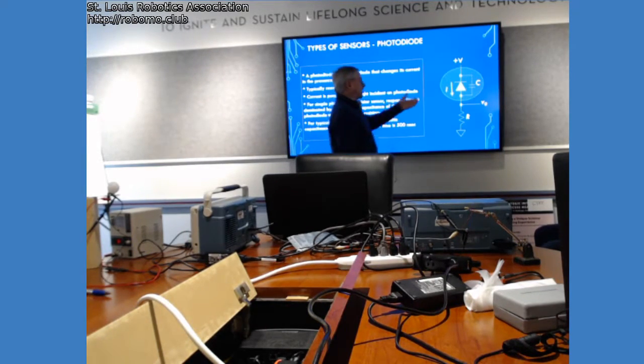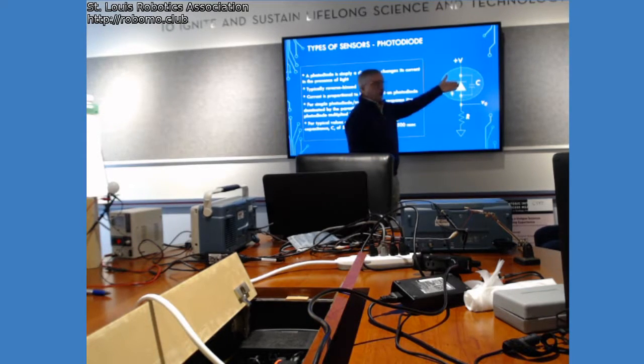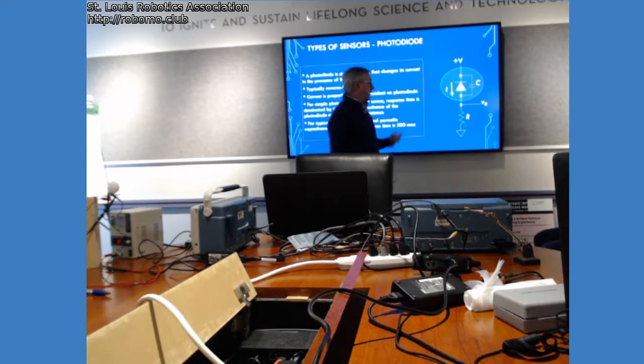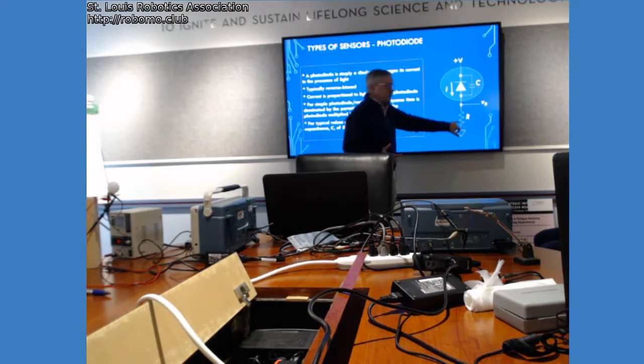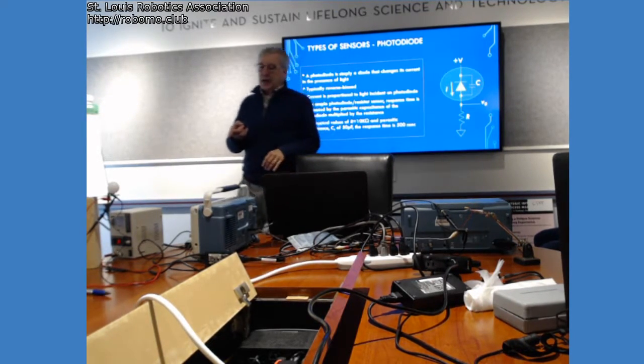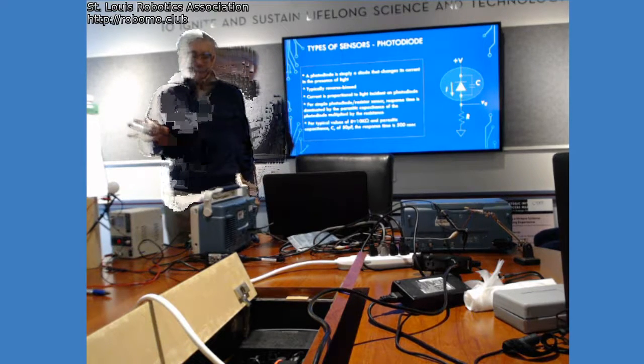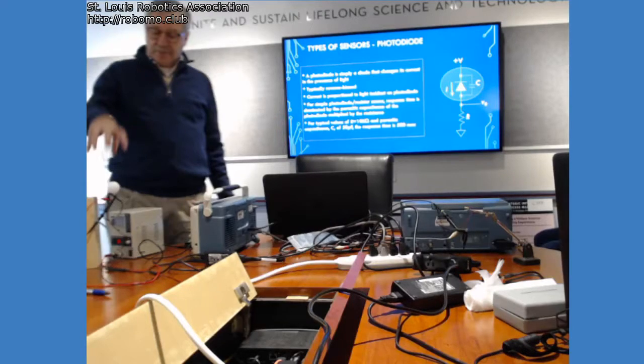Now, if you look at the data sheet, it'll say this photodiode has a 10 nanosecond response, and it very well might. But that's if you had a resistor that was tiny, say 50 ohms or something. 50 ohms in parallel with 10 picofarad, yeah, you could get some really high speeds. But the resistor I'm using on this particular demo is 1 meg.